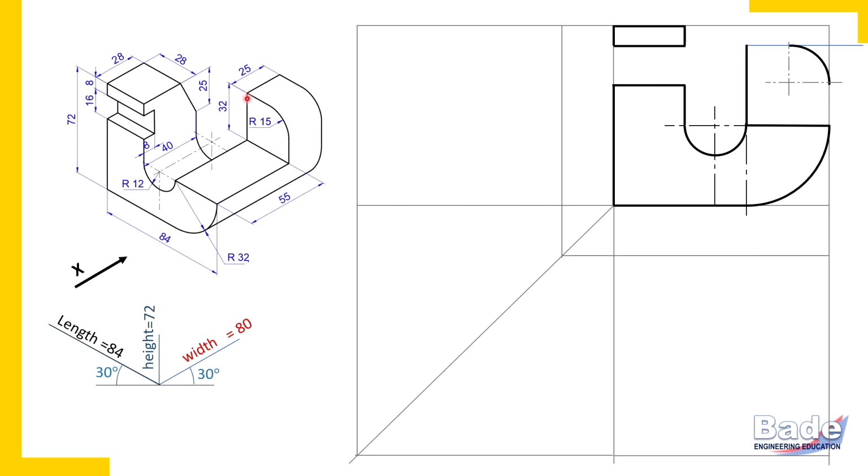Watch this vertical 32 millimeter long edge, this horizontal edge, it is here, and this vertical edge. So we have completed this shape. Is front view over? No, not yet. Check here, there is one more surface. It is partially hidden. This rectangular surface has height 16 millimeter.